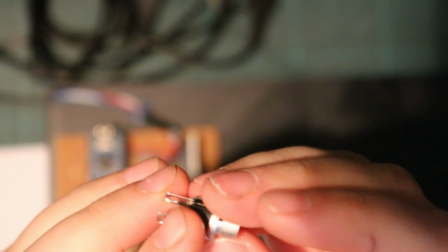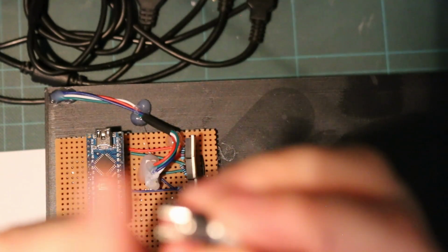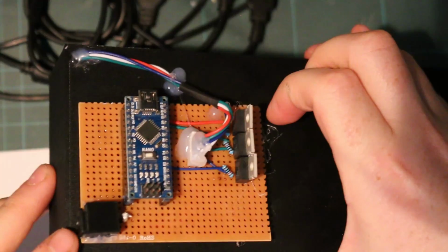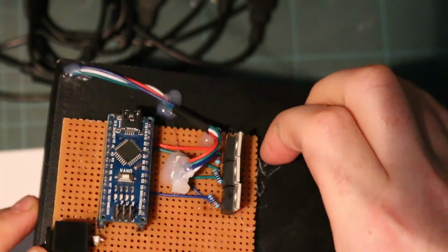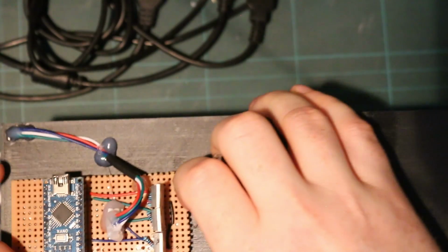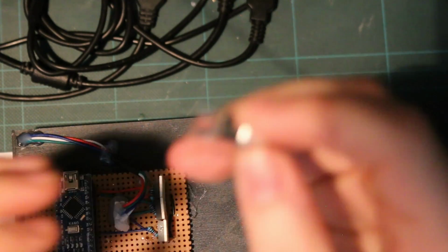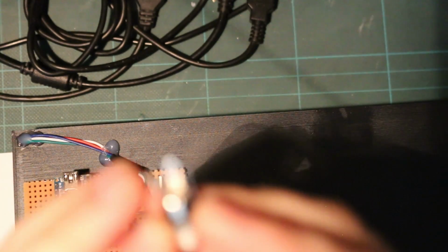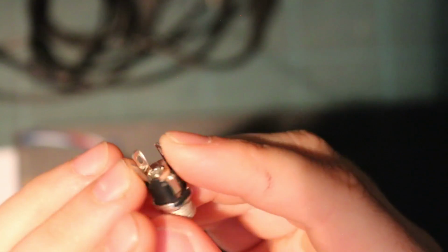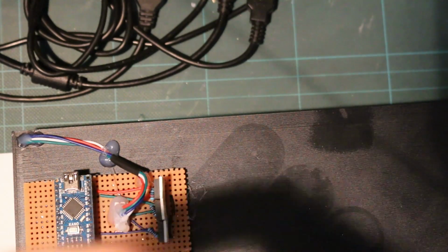so this right here, once it gets into focus, is a newer version of 12-volt jack, just one I bought fresh. This one was salvaged from an old component, so it just came in a handier plastic square tubing, so it made it a little bit easier. But if you can see here, this has 3 pins. 2 of these pins are ground. One of these pins is the 12-volt signal, so 12-volt power.